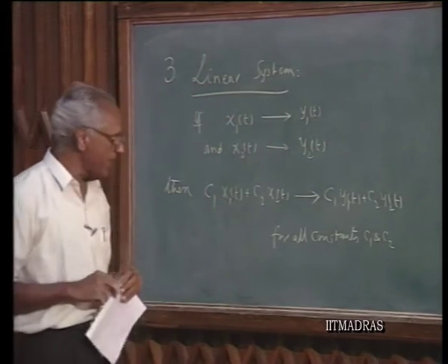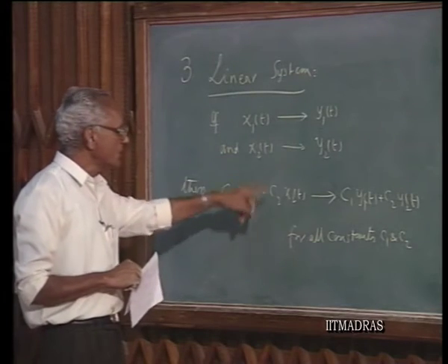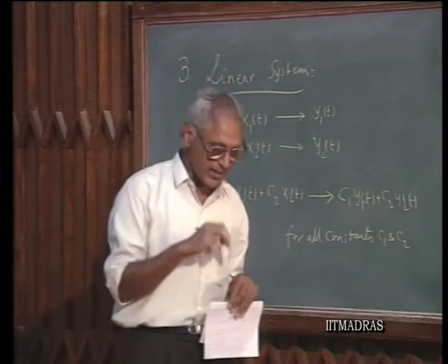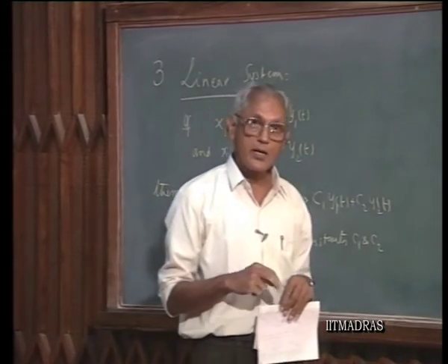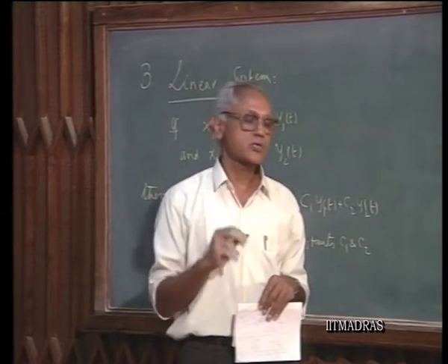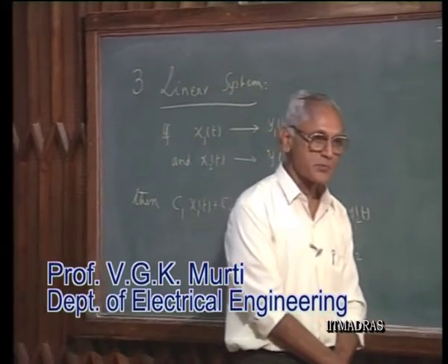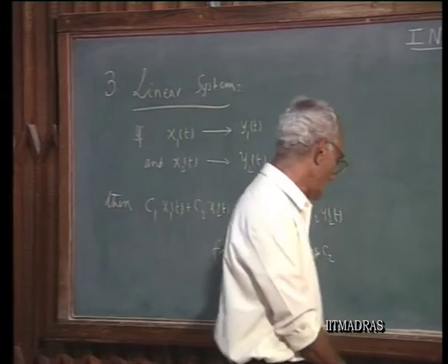But you must keep in mind that this particular superposition principle will be valid, for example, in the case of an electrical circuit with zero initial stored energy. If a capacitor has got some stored energy in it, this principle of superposition will not be valid. Let us take an example.